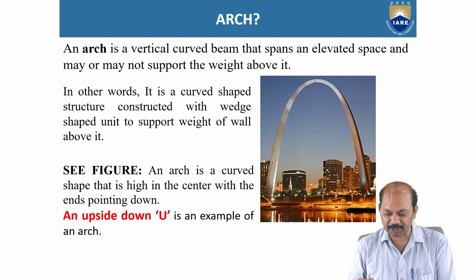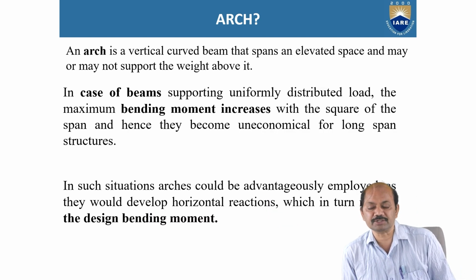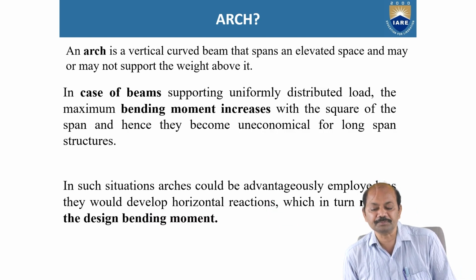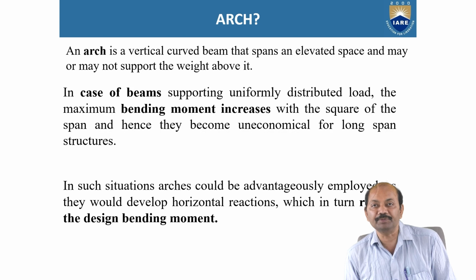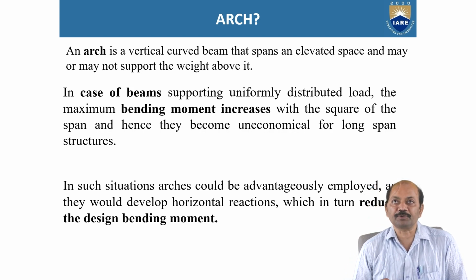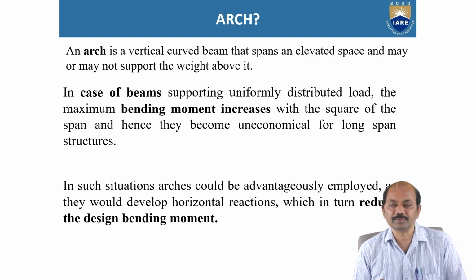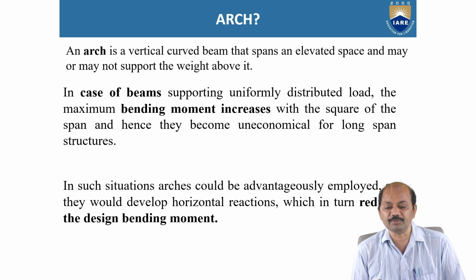Here I will tell why arches are more beneficial than beams. In case of beams supporting UDL, uniformly distributed load, the maximum bending moment increases with the square of the span.